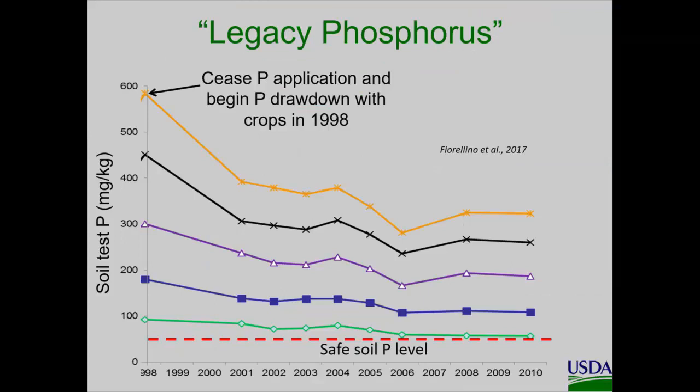Dissolved P is a major target, and the issue with it is that it's very difficult to control once your soils get built up very high in phosphorus. We've got a lot of great best management practices for reducing particulate phosphorus. Quite frankly, anything that reduces erosion will reduce the transport of particulate phosphorus. But even if you have a legacy P soil, if you control 100% of the erosion, you will still leak out dissolved phosphorus every rainfall event that you get.